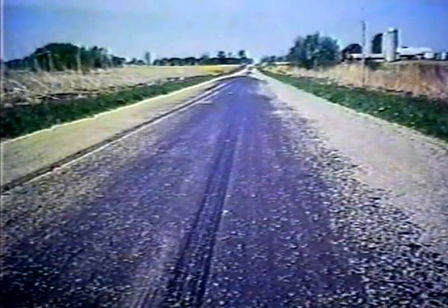Another thing I would mention, raveling should really not occur early in the life of the pavement. It should be quite a while before you see evidence of raveling. Now, if you have a poorly constructed pavement, that is, you have a lot of air voids in the pavement, you don't have a good mix design, and that allows the water and the air to penetrate the pavement, that will accelerate the raveling. So looking at the timing of the raveling in the life of the pavement and the rate at which it deteriorates gives you some clue on the original quality.